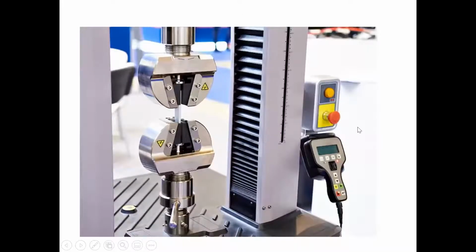This is looking at it slightly differently. Here we have a rectangular specimen, and these 2 large-looking objects are called grips, and they're hydraulically driven. When this is in operation, we press the start button and use a computer here, then the top grip moves up relative to the bottom grip. So either this can move down and this is stationary, or this one's stationary and this one moves up, but the effect is the same. We're stretching the material, we're pulling it apart.